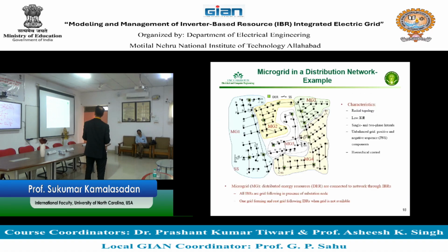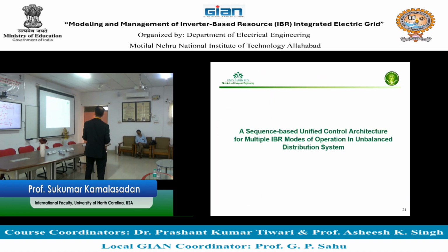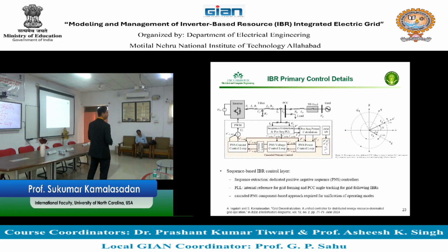One other thing which I wanted to talk about is the hierarchy. So in our lab we developed a method for controlling the inverter, which we call unified, which can be done following and forming depending upon the operation of the inverter, and you don't have to change any control architecture. That is done using unbalanced operation for distribution system, using an architecture utilizing a sequence domain. So it's positive sequence, negative sequence, and zero sequence domain.